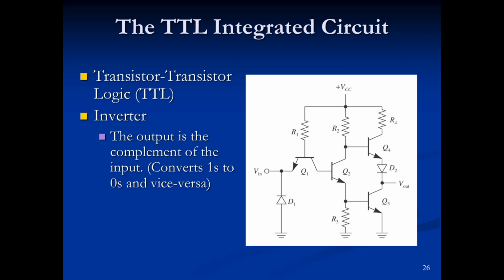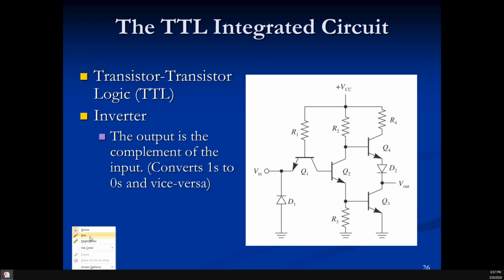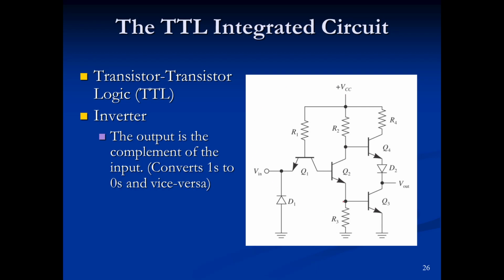It's a way of using transistors to create logic, what we call logic gates, where you have an input. In this example, this is an inverter circuit that they're showing here. But what we mean by logic gate is that we have one input. That input activates these transistors in a certain way. Imagine V in goes into some black box. We have no idea what's inside it, well, we have an idea of what's inside. It's this, but just imagine a closed box where we don't know what's inside. We just see V in go into it, and out pops V out. And this is a logic gate.